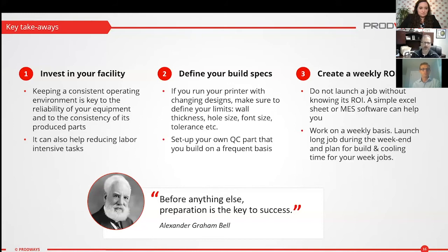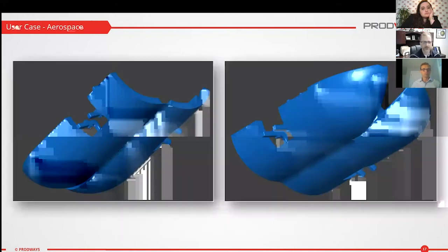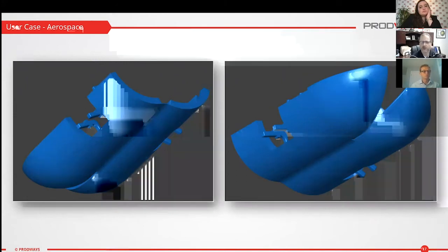Very good points, Alban. Okay, so as we look at a few use cases, as we wrap up and look forward to your questions, this component covers multiple aspects of what the material can be used for. You'll see two posts coming off the one side, in the square window. Those are posts that receive a mating part, and this is polypropylene material, and allows us to heat stake the mating component on. So those square posts get heat staked.